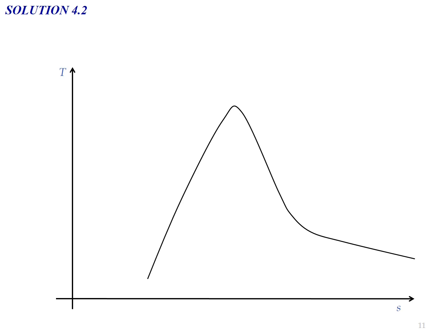Okay, let's say the question asks you to draw the complete TS diagram. What you have to do is draw the TS axis and also the saturation line. And then you need to draw all the constant pressure lines involved in the problem.